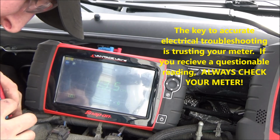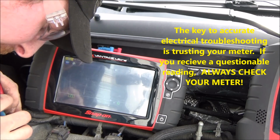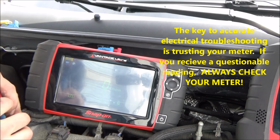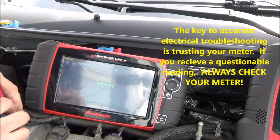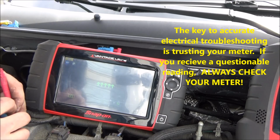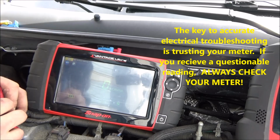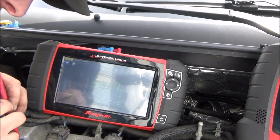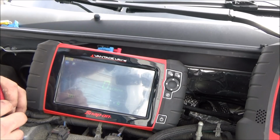Really, that would be like a shorted solenoid. I'm finding that pretty doubtful, based off the fact that we didn't have any solenoid circuit trouble codes for this exhaust side. It was just for the intake. Though here's what I'll tell you guys: whenever I see one of these bad on a car, I recommend both, and that's simply because there's such a high failure item on these.